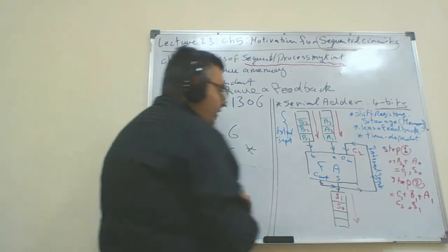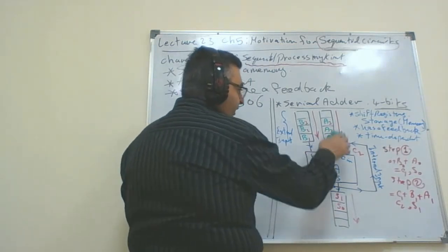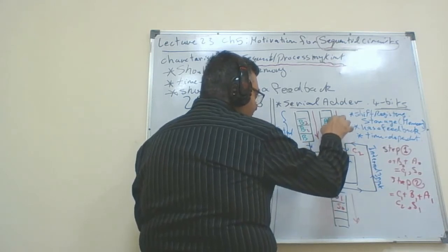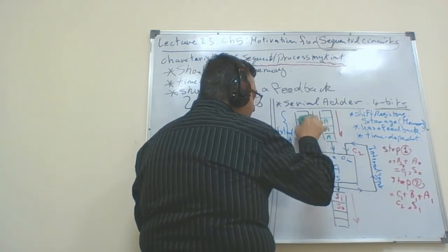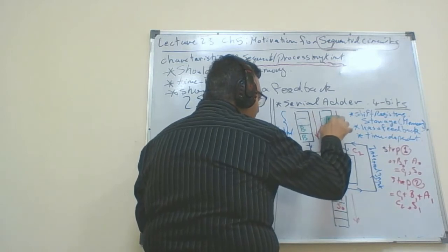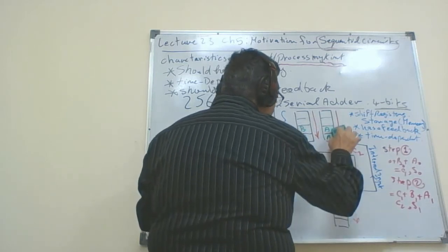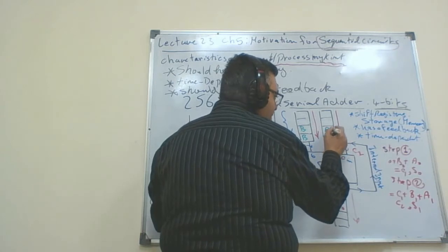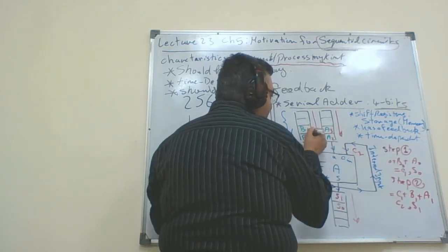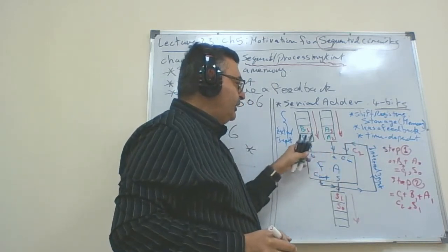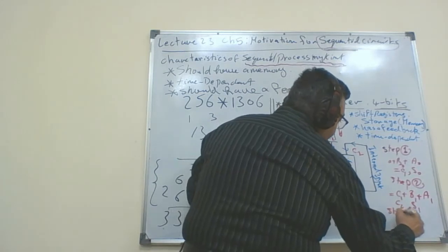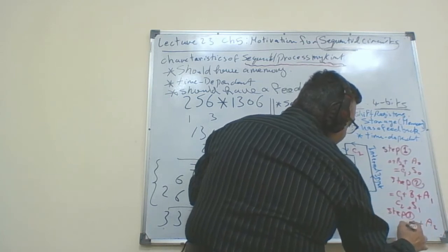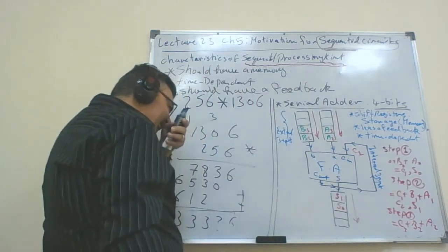Agree? Now going to step number 3. In step number 3, A1 and B1 have been shifted already inside the full adder. So right now at the beginning of step number 3, I would have new values applied on the inputs for my full adder. So right now I have C2 coming from the feedback, and since I already shifted those registers, I would have C2 from here, A2 and B2 added together. Step 3 will have A2 and B2 and C2 added together to give me